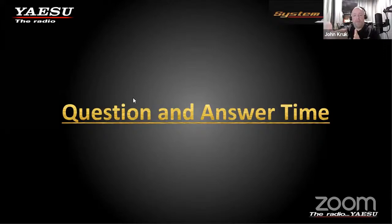So if someone's talking and you have a bad bit error rate, or they're in simplex, even, and you're too far from another user and that bit error rate goes over 3%, you may see their call sign, but guess what? The radio's not going to decode the audio. Same thing with using these bridge technologies, because these things are tunnels, okay? These hotspot devices and everything are tunnels. I've actually done tests myself where those devices are passing bit error rates of 9%. So I'm going into the device at a 9% bit error rate, and guess what? It's sending it out there. The other user on the other end, their radio might show there's a signal, but nothing is being decoded, because the bit error rate is too high.